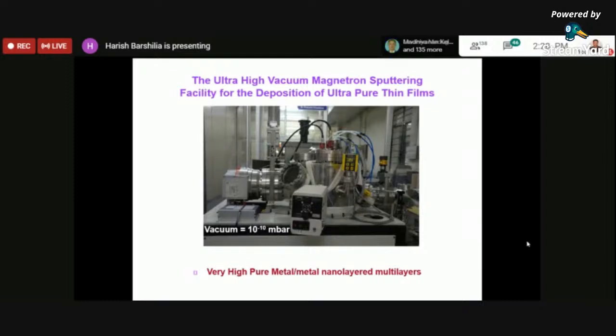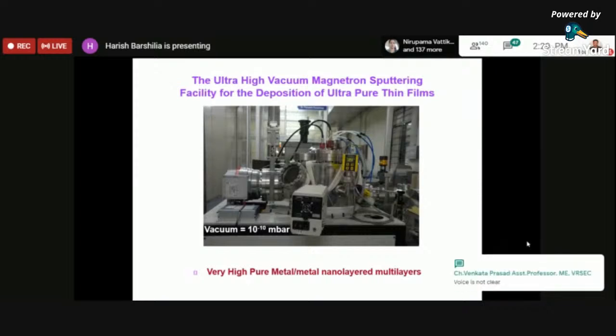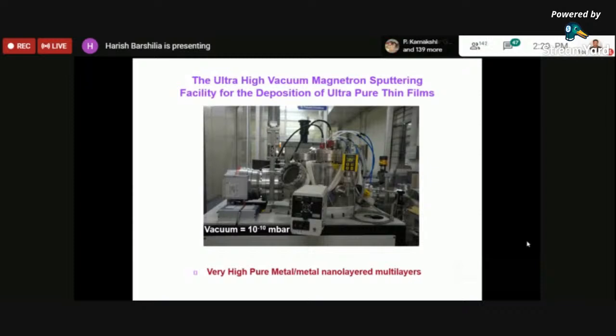But when you are talking about the chips which are used in your computer, like the Intel computer, wherein the 7 nanometer technology is used, there the vacuum levels are very, very high, and we call that ultra vacuum magnetron sputtering system, to avoid other gas molecules getting incorporated into the device. So whenever you are fabricating these high-end sensors, for example, Intel devices or any magnetic sensors, then we make sure that the vacuum levels are very, very high.